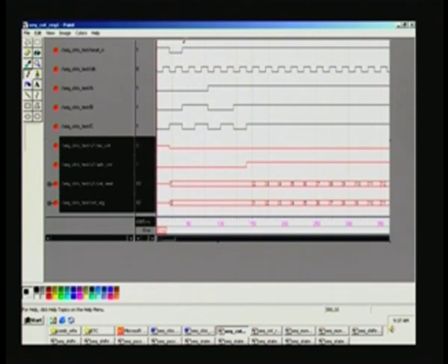When reset occurs, irrespective of the clock edge, you clear the counter as such. This counter reg is here, it is cleared to 0, and you notice that counter next is incremented by 1 right here. So this is what I meant by pre-incrementing, and so ABC are in binary progression being the inputs as such,